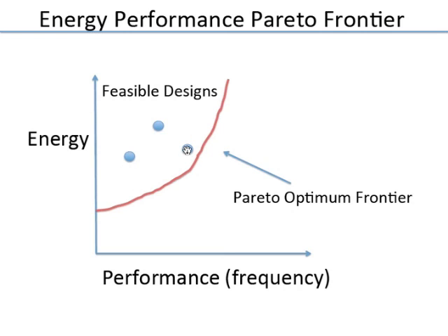Let us say you change non-critical paths to high threshold voltage. You have reduced leakage, so energy reduces, but performance has not changed because the critical path has not been affected, only non-critical ones. So you have come down, which clearly means you are not at the Pareto optimum. You have to make a change and see if it helps you improve without degrading the other things.